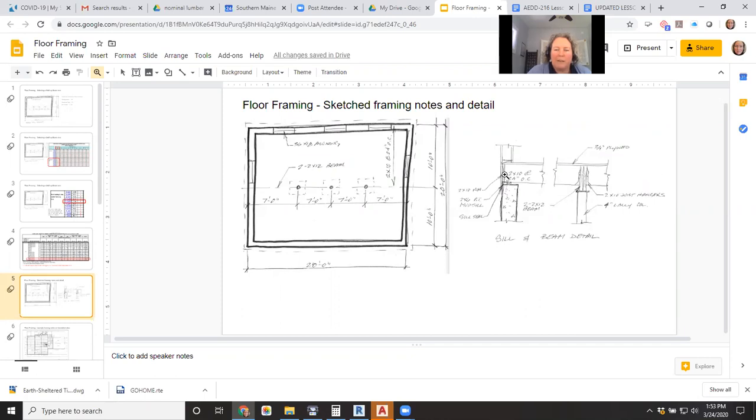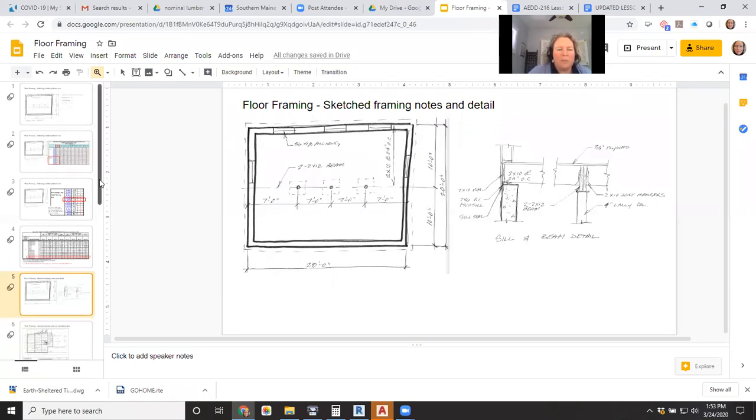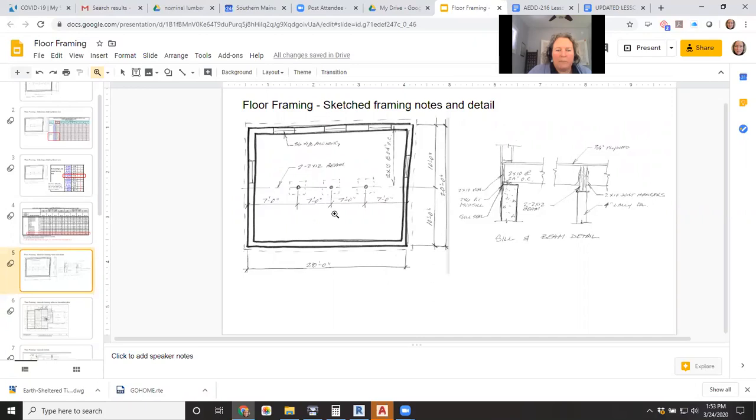That has to stay the same size. So on the other side, where this side is 2x8s, we're going to have to put some blocking underneath that to hold it up. That's all you have to consider. Okay? So just offset spans, you usually want to design to the worst case scenario. Any other questions like that one?